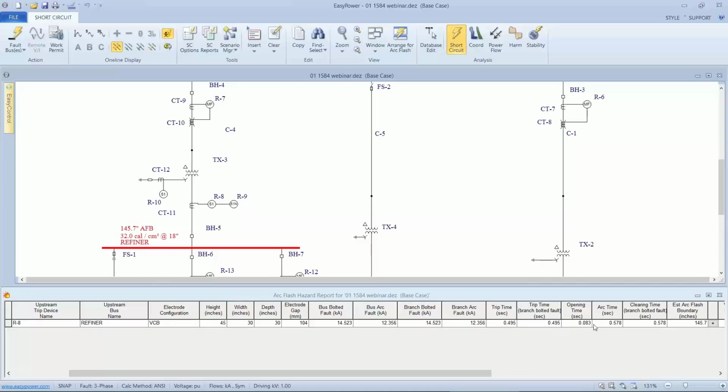This is a lower branch arcing current, so this is probably 30-cycle current. Now, when I say probably, I'm thinking, well, it started off the first cycle at momentary current, then it went for 5 cycles at interrupting current, and then the balance of the time, albeit half a second, was at the lower current.